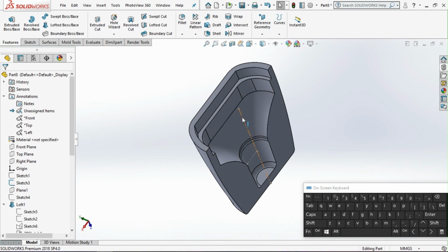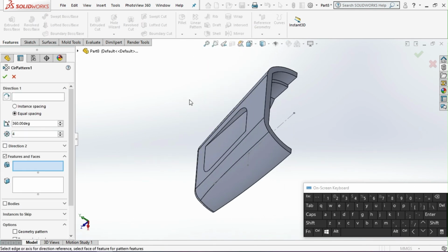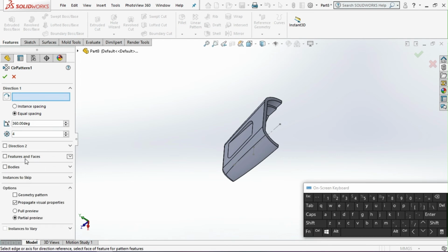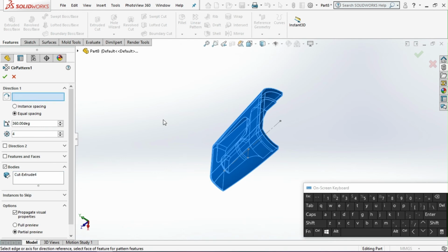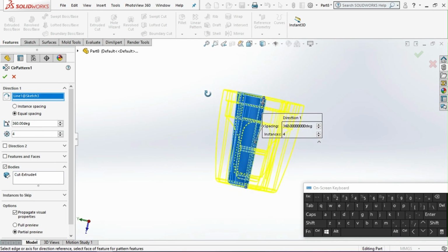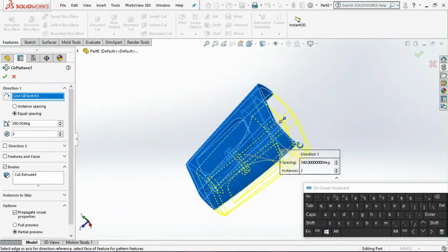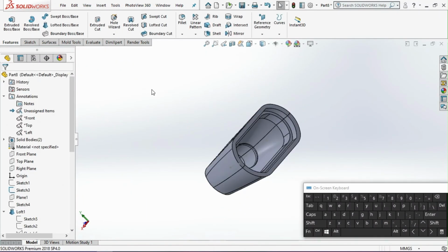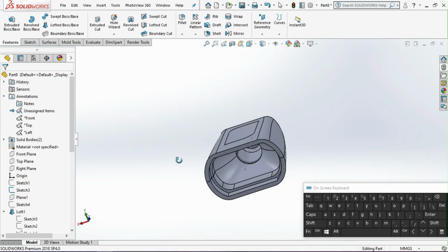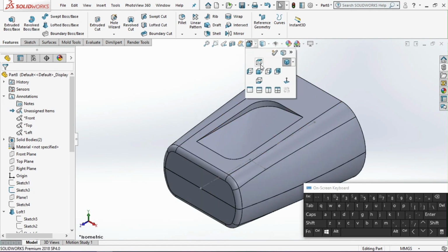So this line, we're gonna use this line as circular pattern. So we choose circular pattern. It's not features but body. So this body, we choose this body. The direction is this line. Wow, it has 4. Actually 2 only. See, 2. Now it's in rotation mode. So just click OK. So you can see here on the top.